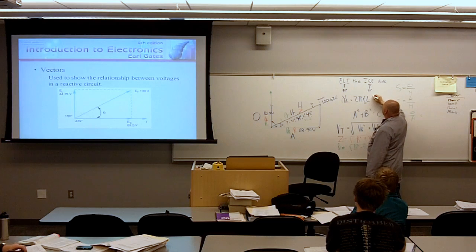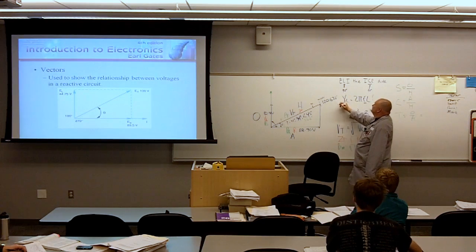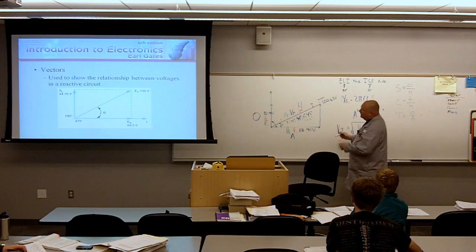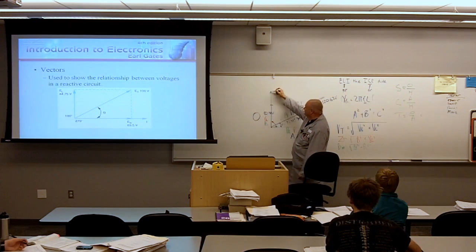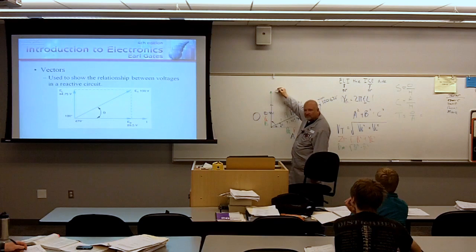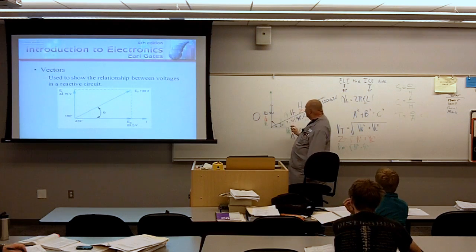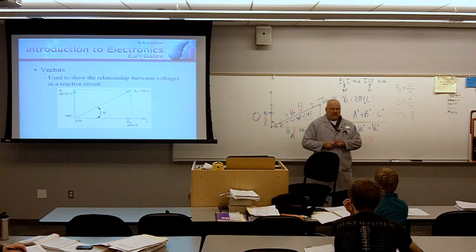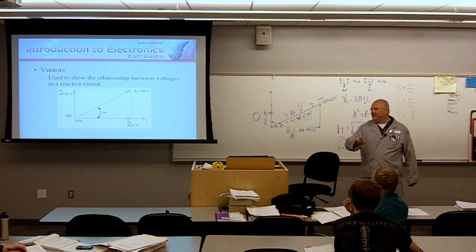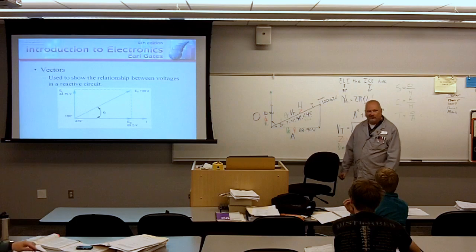If I increase my frequency, so for the same inductor, I increase my X sub L. If I increase my X sub L, my opposite side gets longer. My voltage drop across the inductor gets longer. My power across the inductor increases. Angle theta increases. You see how many questions I could ask you from just this problem alone?